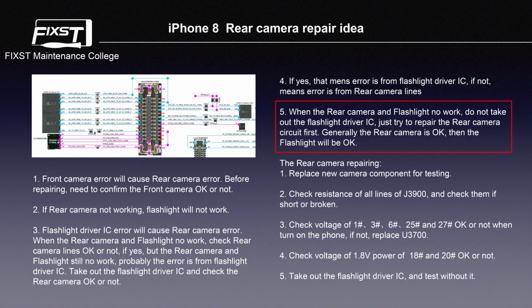Number 5. When the rear camera and flashlight do not work, do not take out the flashlight driver IC. Just try to repair the rear camera circuit first. Generally, if the rear camera is okay, then the flashlight will be okay.